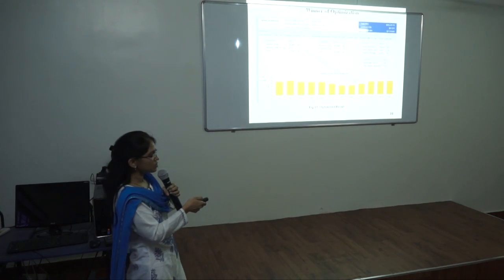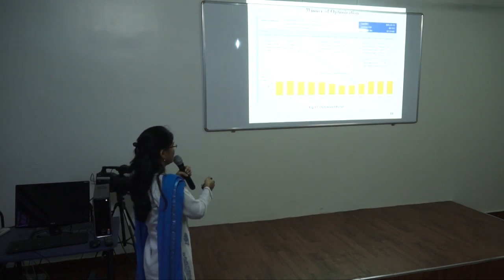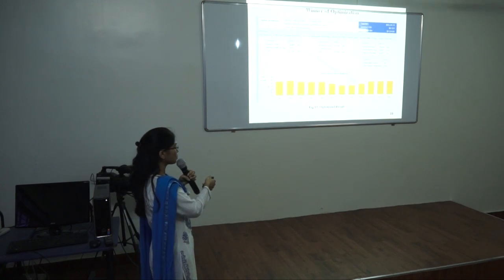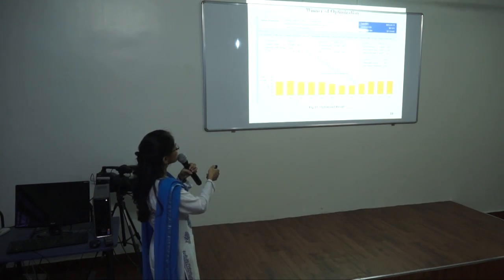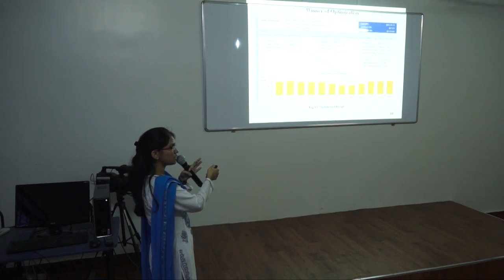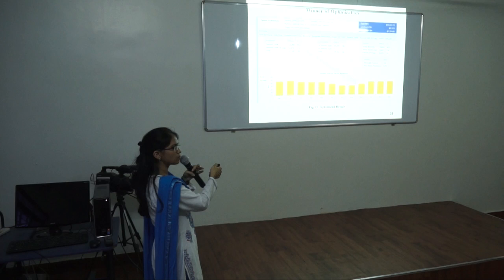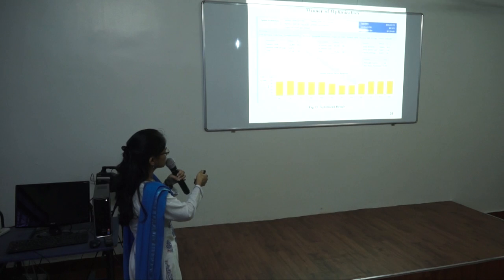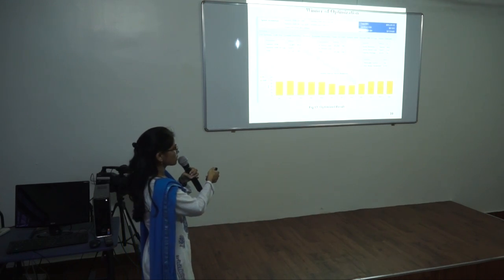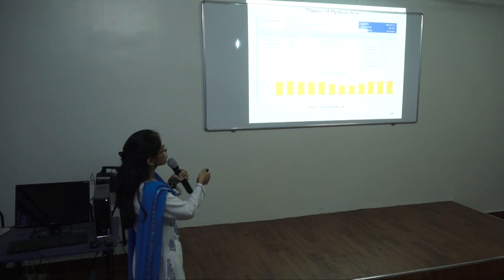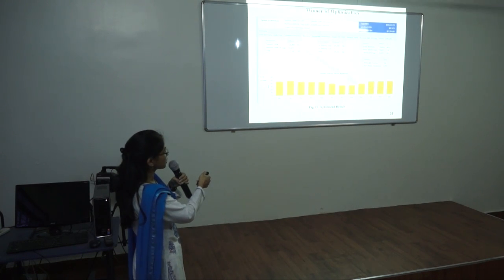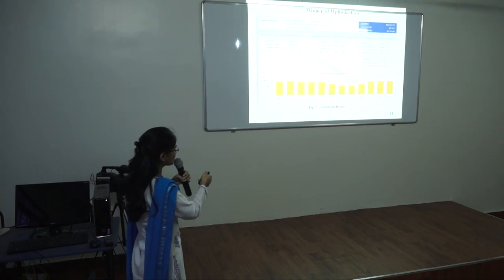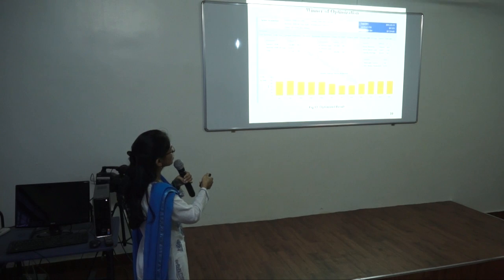On the basis of comparison of economical power systems, type A is chosen as the optimum cost-effective solution given by HOMER for the proposed site, which consists of 225 kW of PV, in which 13 are in series combination and 92 are in parallel combination, 2 wind turbines of 50 kW each, with a battery bank of 6.5, with 25 in series combination and 25 in parallel combination, with an inverter of 155 kW.